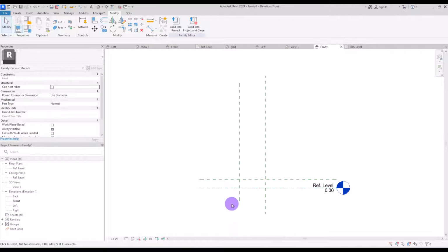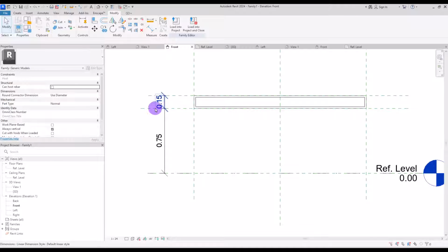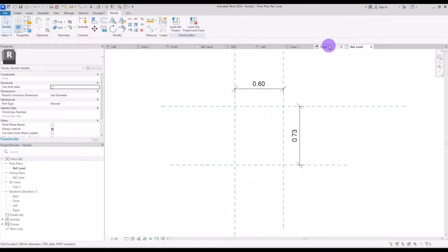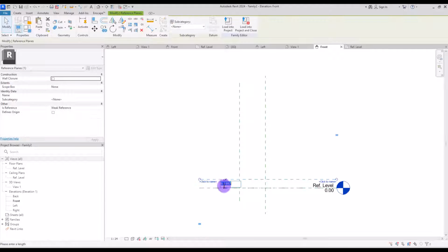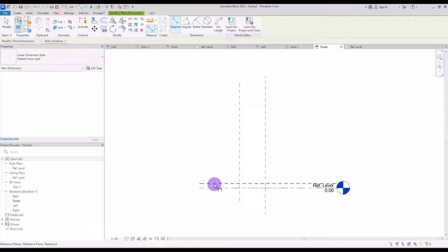And obviously this distance should be less than this 15 centimeter in here. We have 2 centimeter offset in this part and in this part, and with another 1 centimeter offset for its top, we need overall 10 centimeter in here. So I'm going to set it exactly on 10 centimeter and I'm going to create a dimension for it like this and I will lock it.